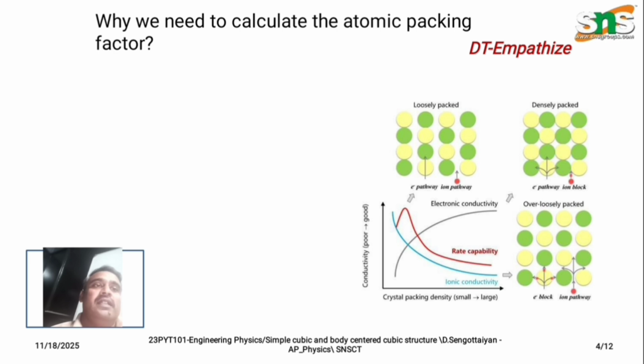So in a crystal lattice, we have to find the total number of atoms present per unit cell and the coordination number of that particular lattice point or atom. Then finally we find the atomic radius and the packing factor. Packing factor plays an important role in a crystal lattice. Based on axial length, interaxial angle and number of atoms, the properties of crystal materials are determined. We all know that in crystalline nature, atoms are arranged in a regular manner and crystal materials have directional properties.